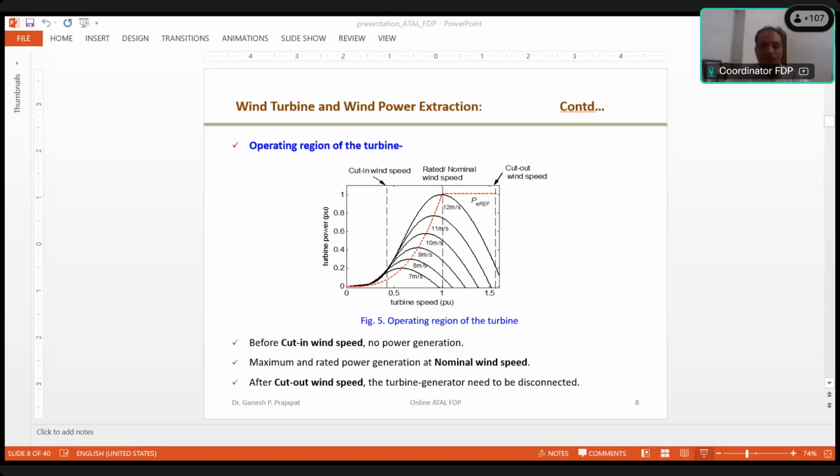In most of the megawatt-rated wind power generating plants, these kinds of generators, the wound rotor induction generators, are used because there is flexibility of control. We can put some control over the inverters or controllers to inject voltage into the rotor of the generator, and then the output voltage and the shaft speed can be controlled from the rotor side.